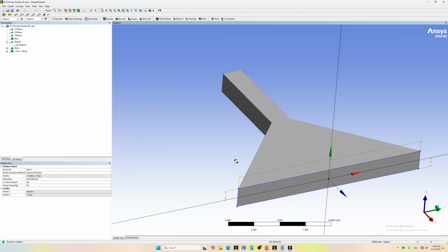All right, so now, from my experience, if you are trying to run a simulation with the outlet so close to the inlet, you'll see that the profile is most probably Gaussian type. So the highest density will be in the middle, and it will be Gaussian shape. So that is most of the time unsuitable for Wakefield accelerator experiments. So let's increase the distance.